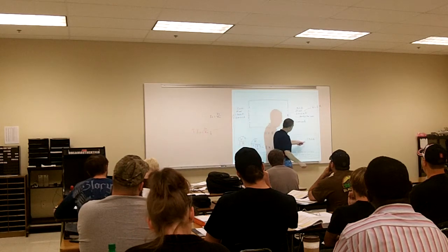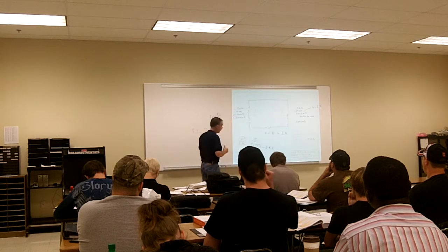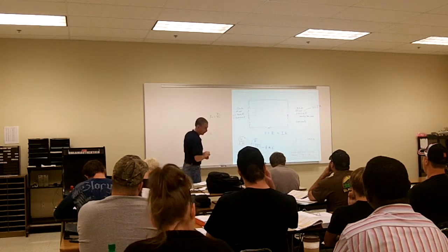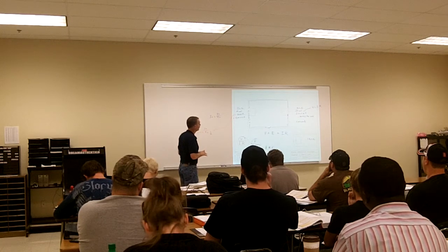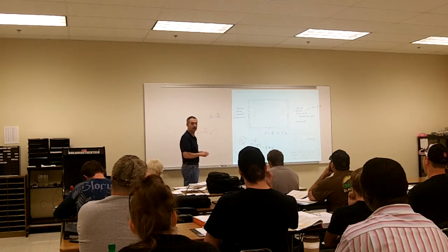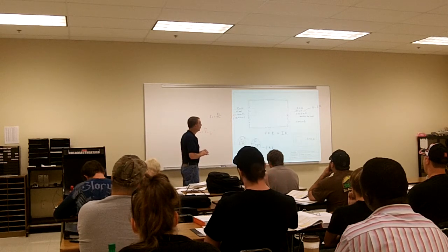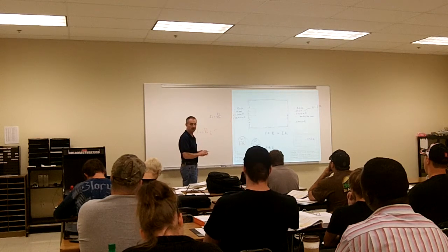So is that an acceptable resistor? Can I throw 118.5 ohms into that circuit? Would that be an acceptable value? What is the percentage of tolerance on that? What is the percent difference on that?